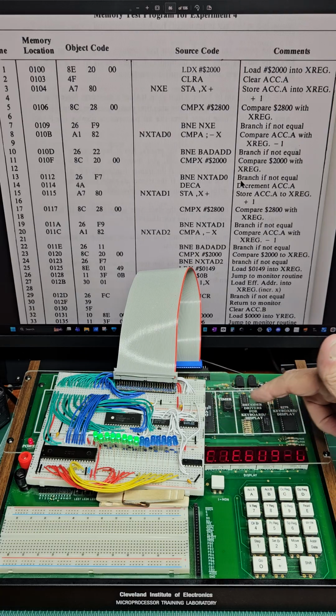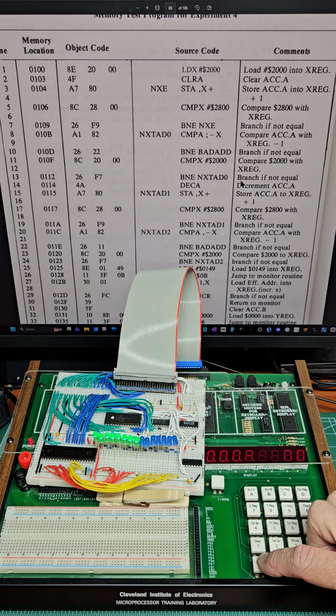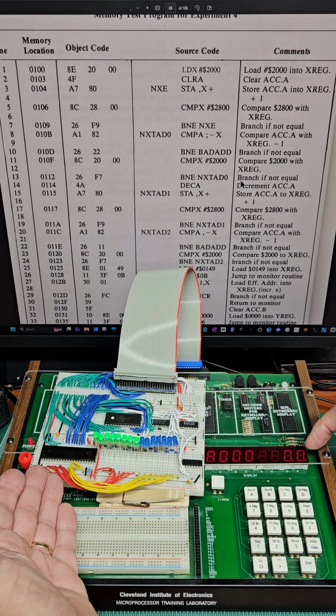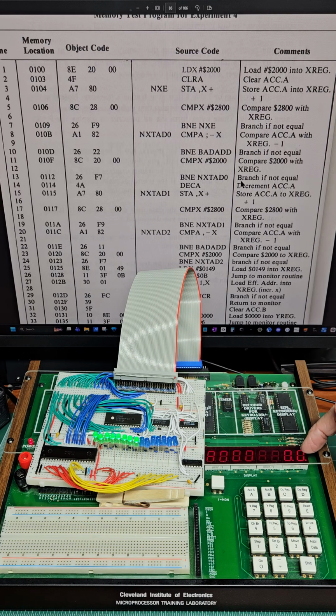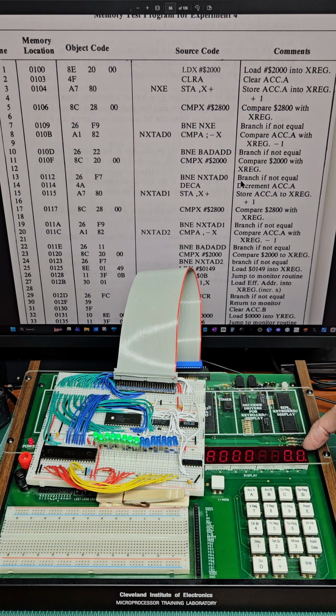The way I do that, I first go to the address. The base address is at A000. It shows 00. Now I want to change the data at that address. And the way the PIA is set up, these 8 bits, this is the A port. If you set 00, it'll set all those ports to read only. You set them FF, it shows them as output. Well, I want to make them outputs because we're controlling LEDs. So I make FF, making them all output ports.